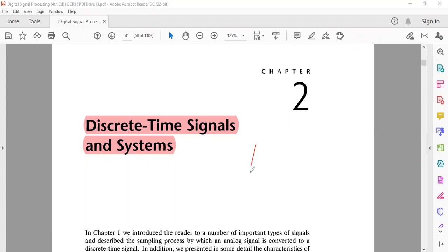has frequencies, okay? If your signal has different frequencies, for example, frequency 1, and there is another frequency 2, and then another frequency 3, but then we realize that F1 is the highest frequency component, then your frequency of sampling Fs should be greater or twice the highest frequency component, which we are saying is F1 in this case.